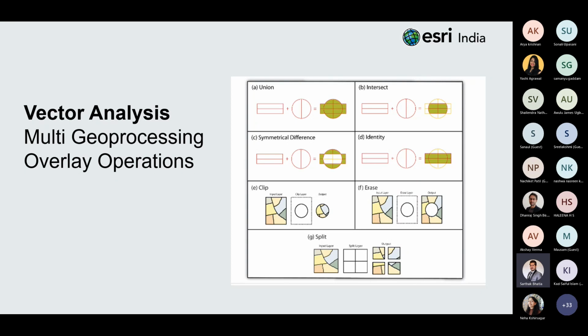Alternatively, the intersection overlay method employs the AND operator, which means that it acts as an intersection and requires a polygon overlay, but it can actually accept line and polygon inputs also. So the output layer covers the spatial extent of the overlay of the 2 features provided as input, and it contains features and attributes from both the inputs. So although it is combining the input attributes, only the section which is intersecting or overlaying for the two features is provided as output.